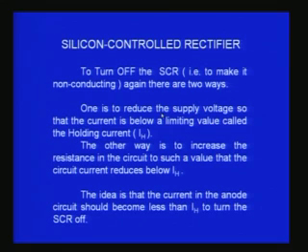Right, you can turn on by using the gate terminal, but what about turning it off, the switch? When you want to turn off, you cannot turn off using the gate. That means if I cut off the current from the gate, will it switch off? No, it won't. So the gate can help only to switch the device on, but it cannot help in switching it off. That is what you should remember all the time.